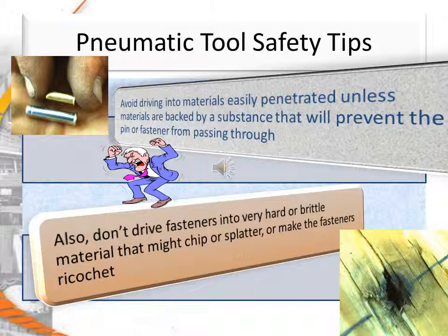Pneumatic tool safety. Always avoid driving into materials easily penetrated unless the materials are backed by a substance that will prevent a pin or fastener from passing through. Don't drive fasteners into very hard or brittle material that might chip or splinter or make the fasteners ricochet.